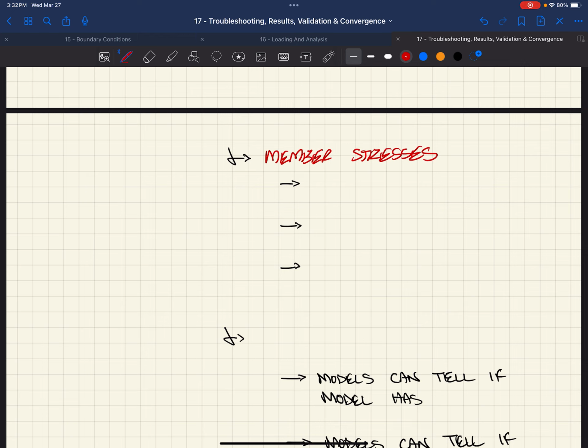And one of the other assumptions we've made in our derivations, when we went to the principle of total stationary potential energy, we made this assumption that we have a linear elastic material. The internal strain energy was one half stress times strain. And so we made this distinction that we weren't going to go beyond yield. And so if some of our member elements do go beyond yield, that could be a potential problem. That may or may not be a problem though.